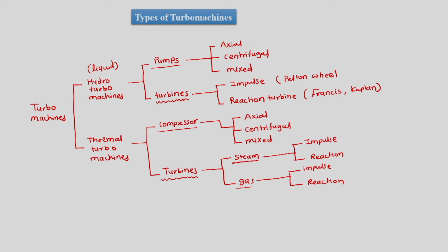But then, the turbo machines are one class of machines, and the complementary machines to those are positive displacement machines. As we know, reciprocating machines are generally called positive displacement machines. The major concern in designing positive displacement machines is that the flow should have one way entry and one way exit. So, there is only one path in which the flow will go; the flow cannot take a reversal. Such machines are called positive displacement machines in general, and it constitutionally happens for the reciprocating machines. So, reciprocating IC engine, reciprocating pump, reciprocating compressor turn out to be positive displacement machines.